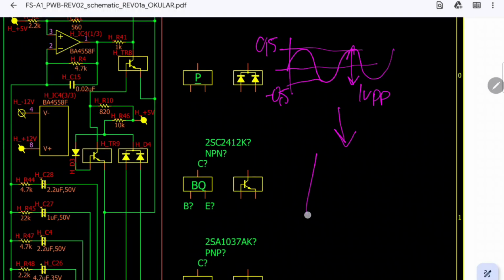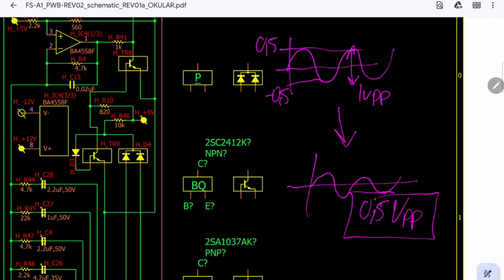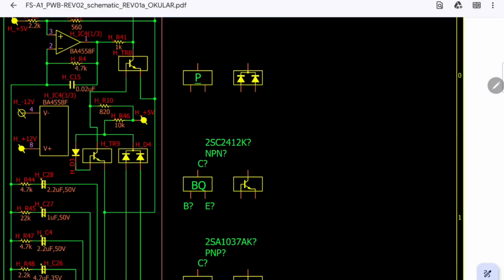This will be turned into something smaller, which would be like 0.5 volts peak to peak, and this is within the specs of your SCART connector. But we know that the circuit is adding all the other inputs, so what happens with them, I haven't tried, but I would expect that it saturates if all of them are at the maximum level.